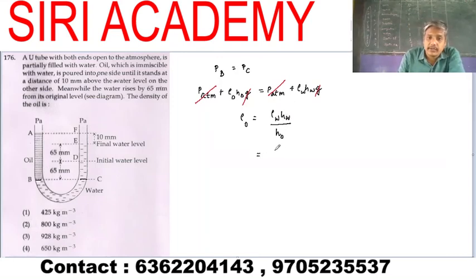So density of water is given by 1000, and height of the water column is 65 and 65, that will be 130 into 10 power minus 3 meter. Height of the oil column is 140 into 10 power minus 3 meter. Upon solving this, you are going to get it as approximately 928 kg per meter cube. So the correct option is third.